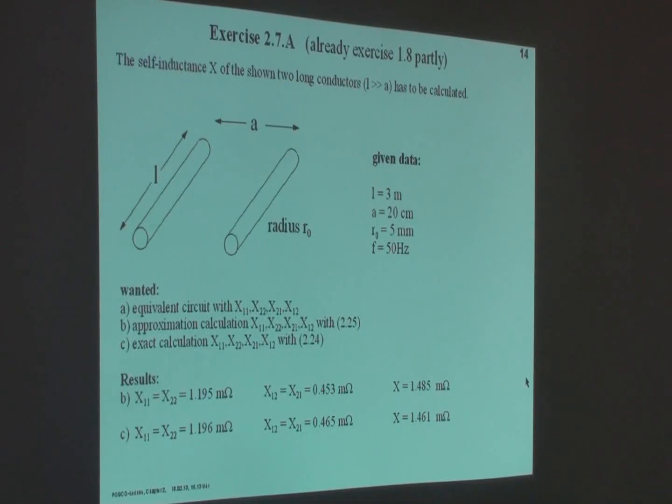So the problem is if you have parallel conductors or you have copper plated electrode arms, you have to calculate the GMR. And if you have the GMR, you can calculate the reactance like this.